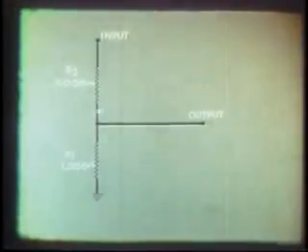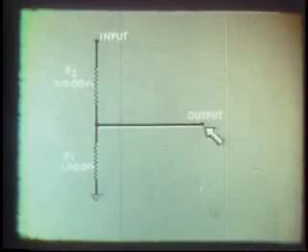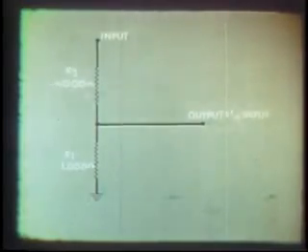This is a simple voltage divider. The total input resistance is 10,000 ohms. The resistance at the output terminal is 1,000 ohms, 1/10 the total input resistance. Therefore, this voltage divider will divide by a factor of 10.